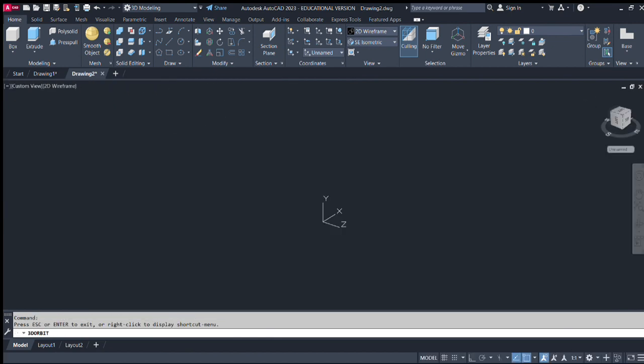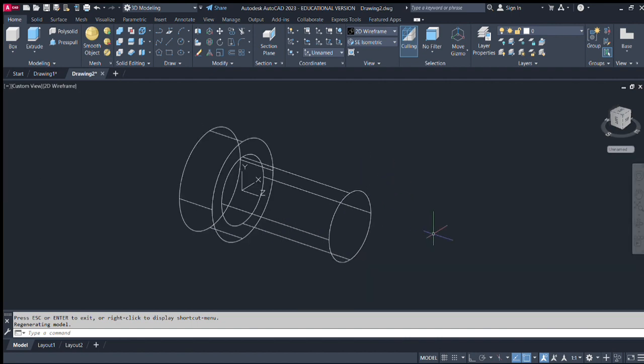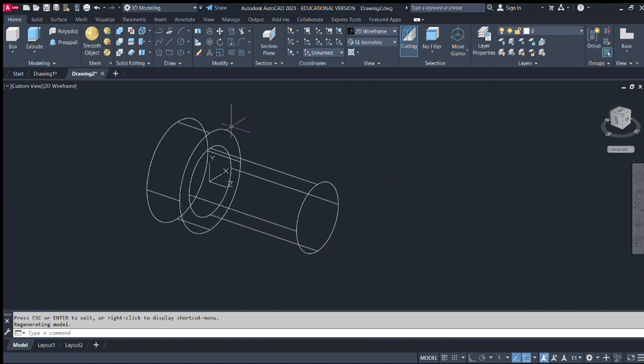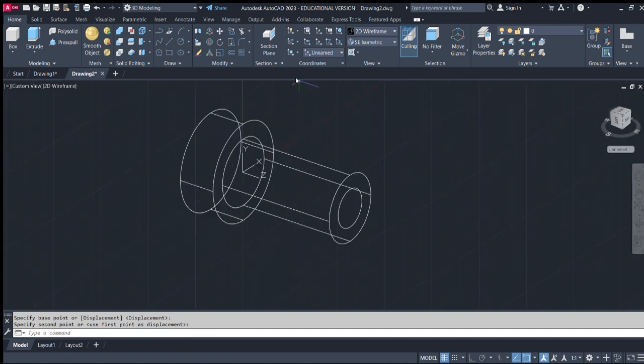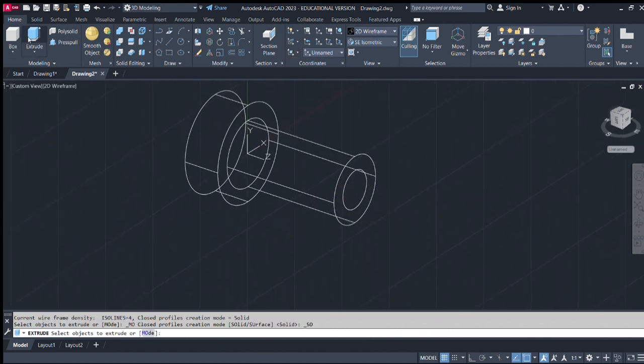Now here you have an option to go back to the right plane, or since you are already in the plane in this orientation, you can make a circle anywhere in that space on the plane, diameter 25. Okay, and you can move the circle from its center and align it to the face of the next plane we wanted. In this case you did not change the planes here. It will be easier. We go to extrude and we extrude this by 30.